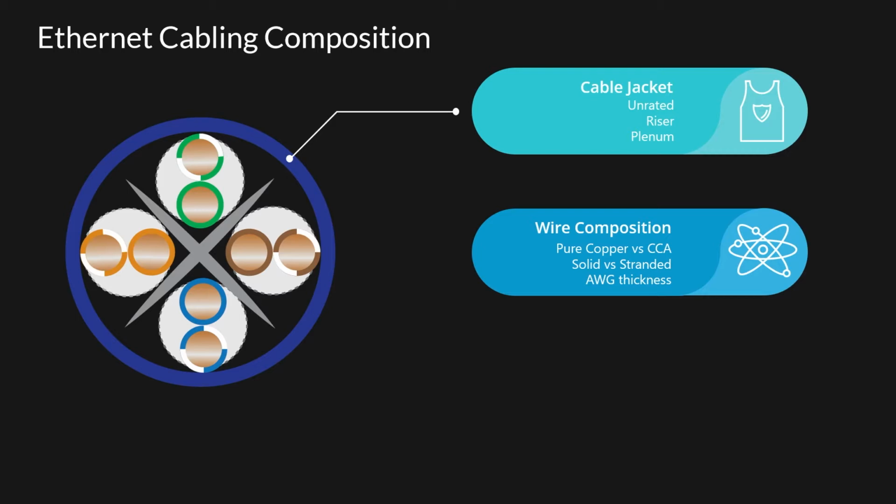That way you can flex it around and the wire isn't going to eventually metal fatigue and then snap on you, and then you don't have a connector anymore. If it's stranded, then it's flexible, and that's the way basically all sorts of things are made. Electrical extension cords are made the same way. If you want a cable to be flexible, you use stranded cabling.